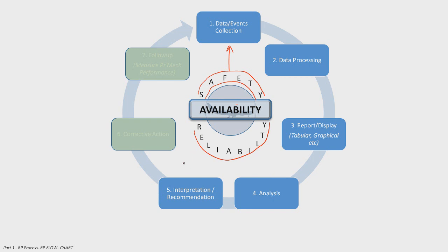Let's say the last 18 months, our reliability program tells us that we have part number XXX-1 and scheduled removal is, I don't know, let's use 1000 flight hours. Anyway, this is an example. Now a DSB engineer comes and says, as per manufacturer and supplier documents, if we install Dash 2, the reliability will be 3000 flight hours. Now we take this information and present it to the Airline Reliability Board.